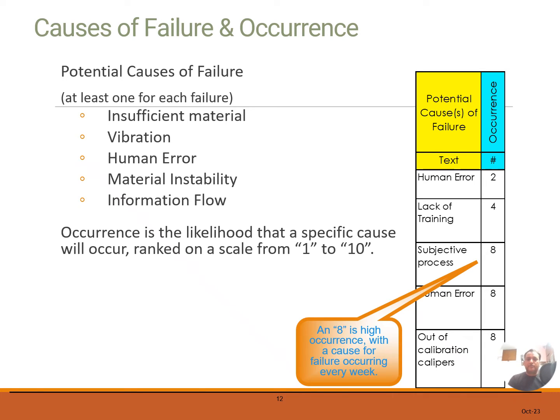The potential causes of failure are identified. This refers to all the things that may be responsible for the failure mode, or how the failure could occur. Potential causes of the failure could be any design weakness or the process changes or variables. Once the potential causes of failures are identified, then the probability of occurrence is ranked.